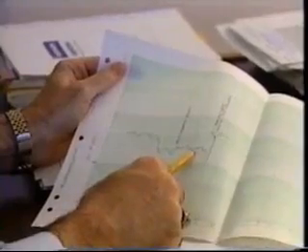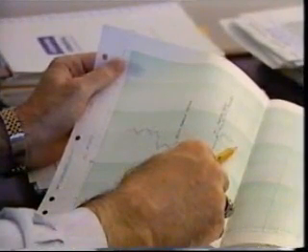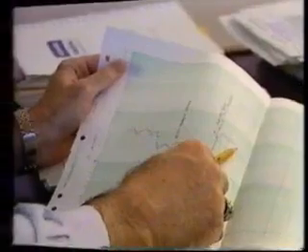The most important consideration in this treatment was to recover the treatment load as soon as the treatment was finished and to ensure that there would be no subsequent emulsion problems, which was done by the use of surfactants and laboratory testing prior to the acidizing treatment. How successful was the treatment? After the acidizing treatment, you will note that we restored the production of the well to what it was when the well was initially completed.